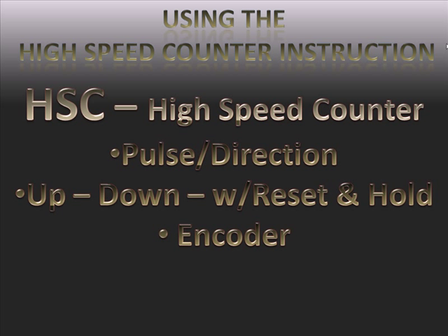With the high-speed counter, the electronic circuit counts transitions as fast as the rise and fall time of the solid-state circuit will allow. In other words, it's a physical limitation based on internal capacitance and inductance. For the MicroLogix 500, with the filter set as low as possible, set to 0.075 milliseconds, 75 microseconds, this is approximately 6600 Hertz at 50% duty cycle. So the high-speed counter electronic circuit will count up to that frequency, 6600 Hertz.